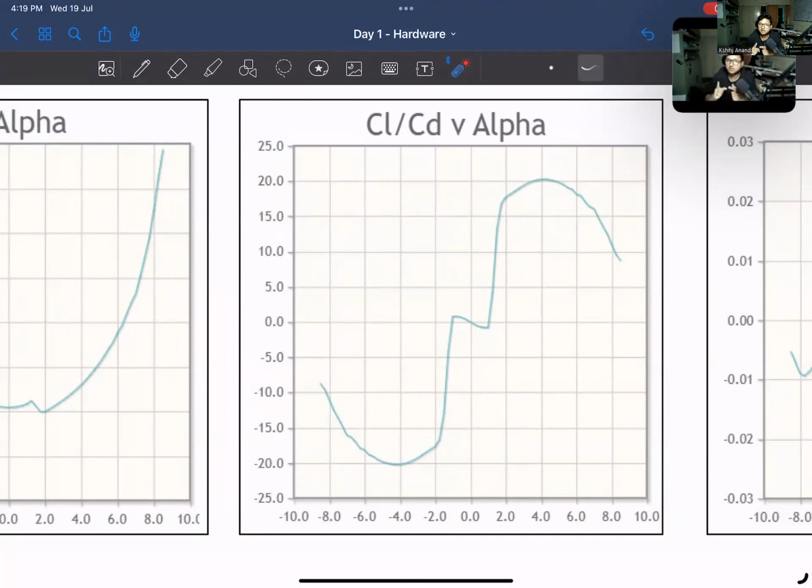Your drag is being countered by the motor that is spinning and producing thrust. The motor can spin only up to some maximum RPM, and beyond that it's not going to produce more thrust. If it reaches the limit where drag almost overpowers the thrust, it's not safe.